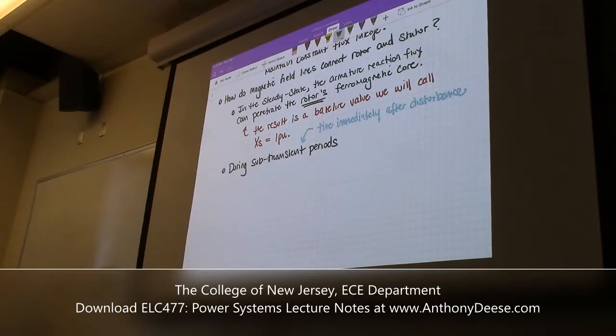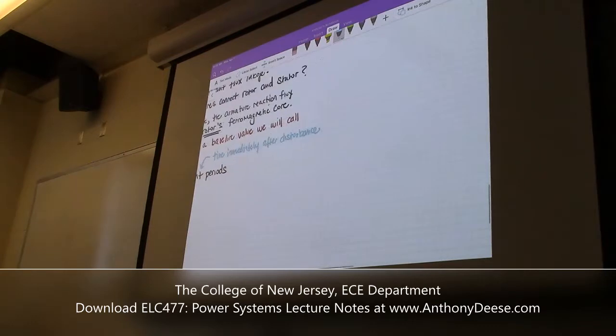when the dynamics are fastest moving. So we're going to go from steady state, disturbance occurs, we have subtransient, which is the very, very fast movement. Some of those dynamic behaviors will settle down, which will lead us to the transient period, which is a slower movement, and then we get back to our steady state.